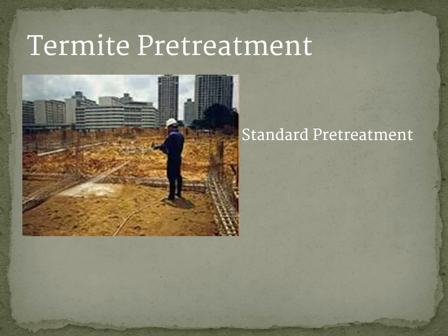And one thing that's very important for us to all remember is that most of the time these job sites do not have water on them. So it's a really good idea to go ahead and fill your tank up full of water and not mix the termiticide until you get on the site, because you don't want to have a spill along the way. But this will help you when you get there already have the water you need. Then you can mix your termiticide and you can go ahead and horizontally treat this whole area within the walls.